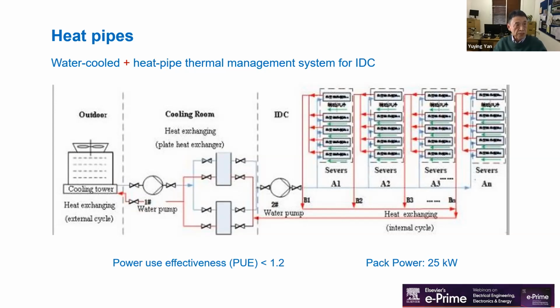So this is an example of application of combining heat pipe and the water cooling system for data center cooling and thermal management. The principle is using heat pipe to accurately position under the hotspot, and heat pipe almost isothermally delivers heat to the water channel heat exchanger.